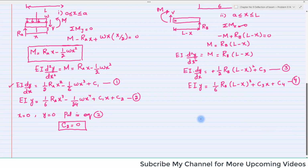You can apply the boundary condition. We have the second boundary condition that at x is equal to L we have y is equal to 0. So put in equation 4. Clear? So y will be 0 and x is equal to L. This will be 0. So we will only have 0 equal to C3 into L plus C4. So C4 will be equal to minus C3 times length.